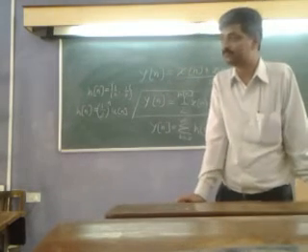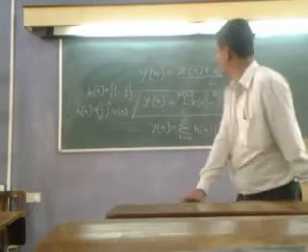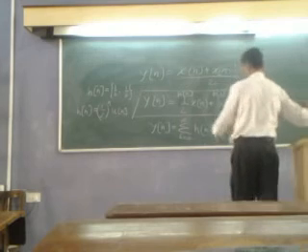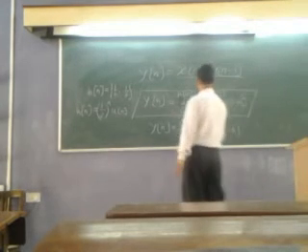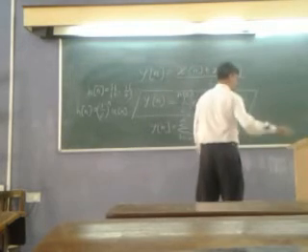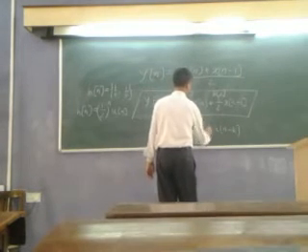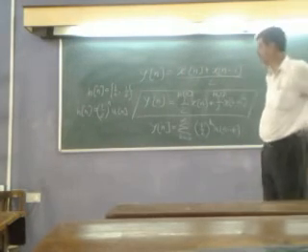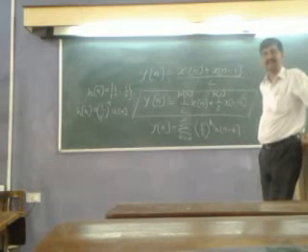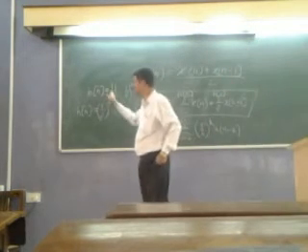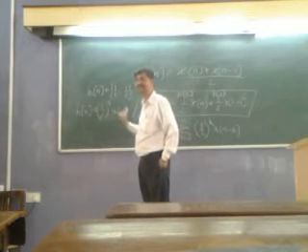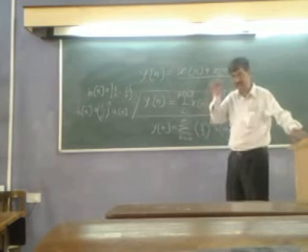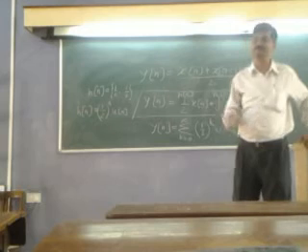Is it okay? So in that situation, what would be Yn? Yn would be the summation of half raised to k into Xn minus k. So in this case, Yn is an infinite summation. Here Hn is infinite in length, so Yn is an infinite summation. For every single value of y, you have to compute infinitely.